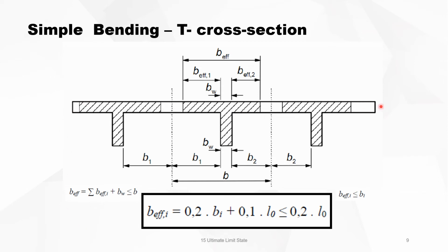Consider now a floor slab supported by beams, and you have consecutive T-shaped beams to carry the loads of the slab. Now the effective width, where you can calculate the beam width, is not just the center line of two beams, because this is too wide. The compressive force is not constant over this width.